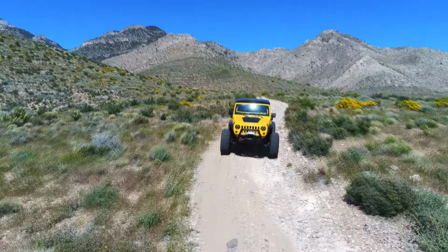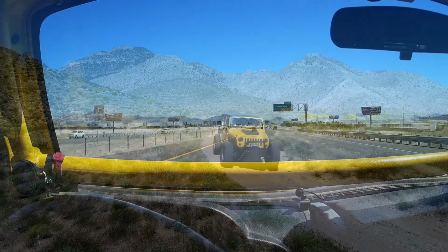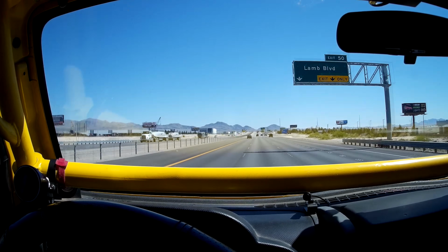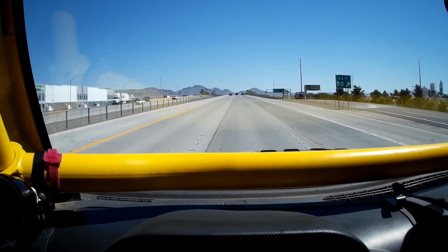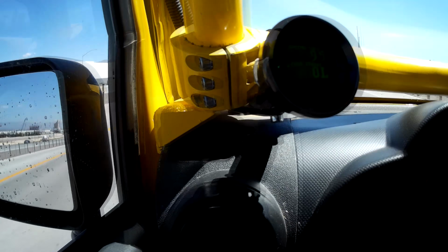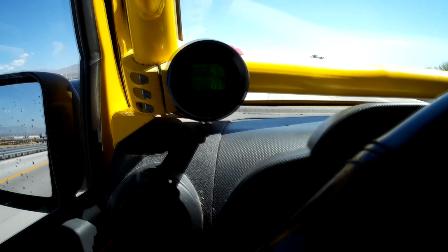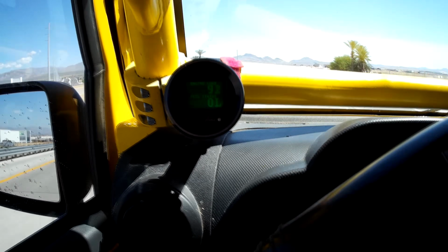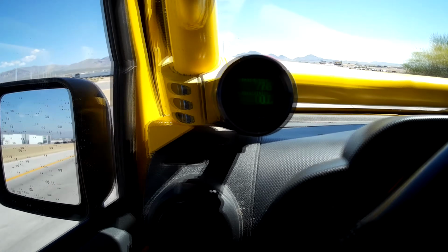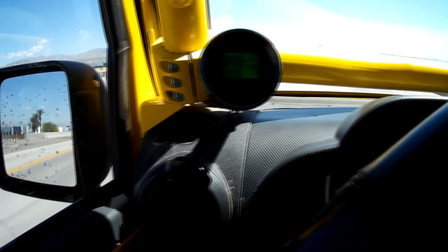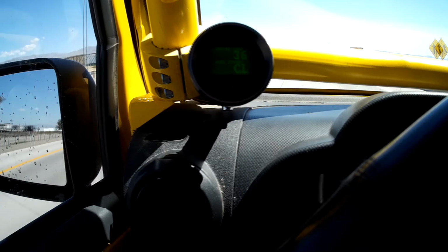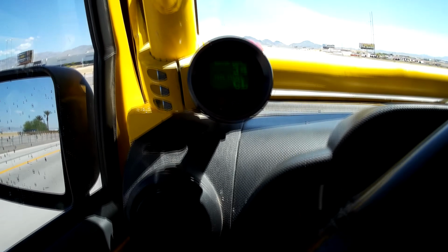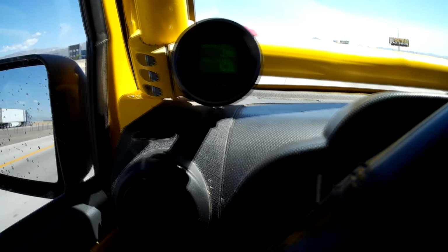If we had a 6.2 liter engine or a supercharged engine, we might be able to stay in closed loop longer. Now I'm going up this grade, and you can see that we did kick back into open loop. And you ask, why am I telling you all this? Well, a lot of you guys are concerned about economy on the highway. And the reality is, just by backing off a mile per hour or two, you can stay in closed loop and increase your mileage significantly.